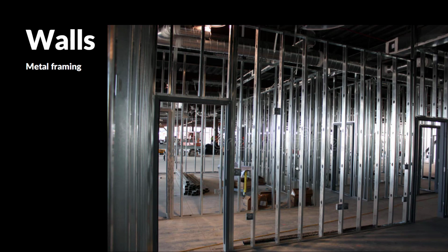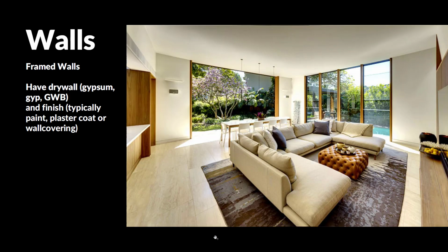It's certainly doable, but primarily used in commercial applications, relating to cost; they're lightweight, and they don't combust like wood beams do. But you'll still see the same types of ideas with the floor plate, the vertical studs 16 on center, and so forth, but out of metal instead of wood.